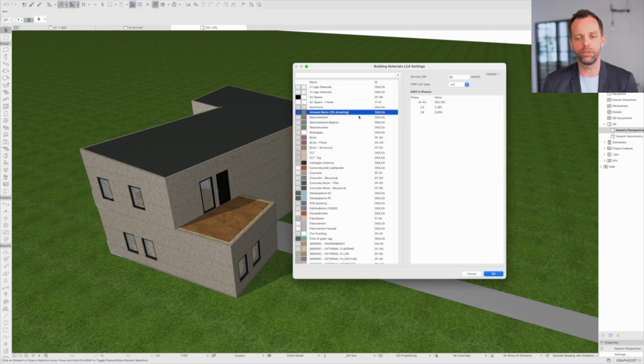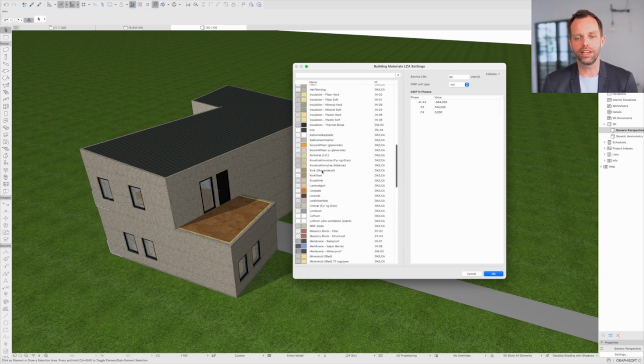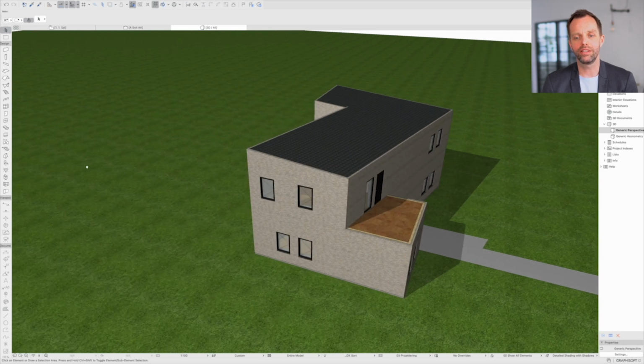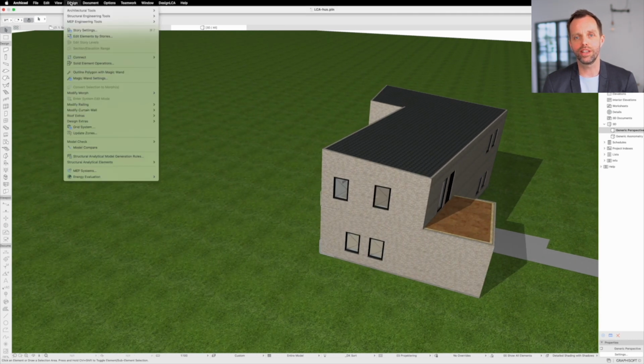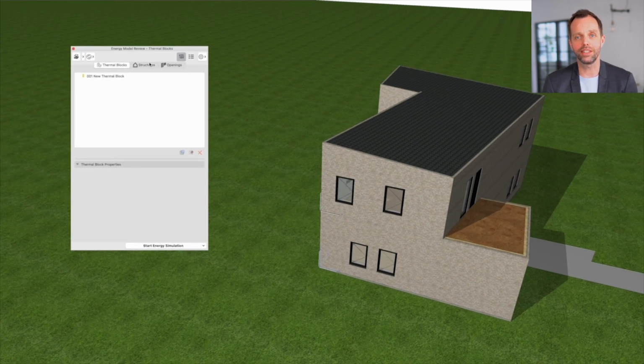I can look at the material browser where I have EPD data with the CO2 footprint from the different phases of each material and also the surface life. And one of the clever things about Design LCA is that I can enter this EPD data by square meters, by cubic meters, or by kilograms, in the same way as the EPD has the units, with the same units as the EPD.